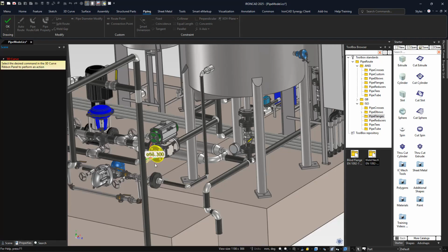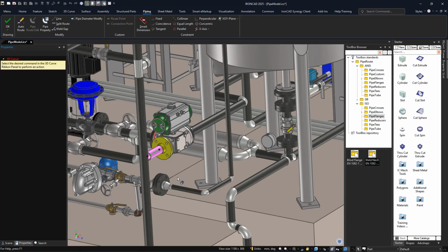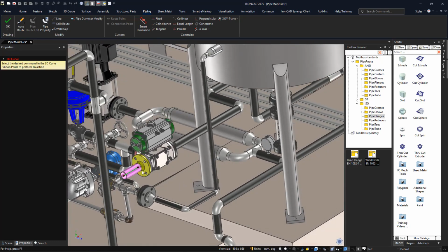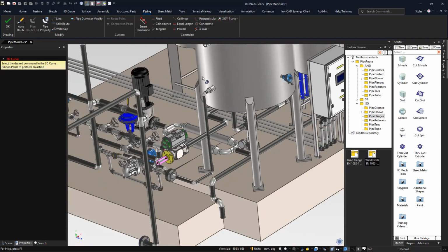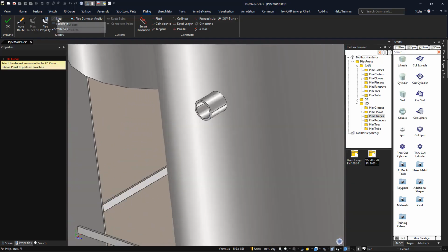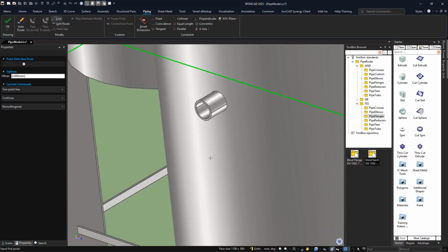And now it'll actually start us into what we call the 3D curve mode. In this case, it's really just talking about line geometry. And we already have a starting point here for our curve, which we're going to use as our starting point, and we're going to actually use another line up here. So we're just going to zoom in here, go to our line command on our ribbon bar, and we're going to pick that starting point as well.